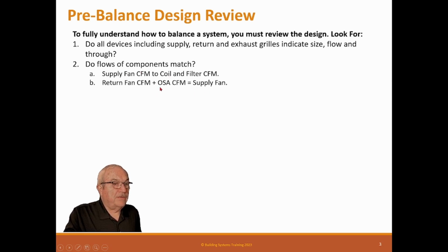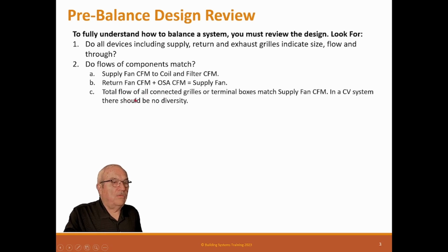Return fan CFM plus outside air CFM equals the supply fan, to make sure that's going to work, because if not, then the return fan CFM has to be less. So those need to add up. Total flow of all connected grills and terminal boxes must match supply fan CFM.